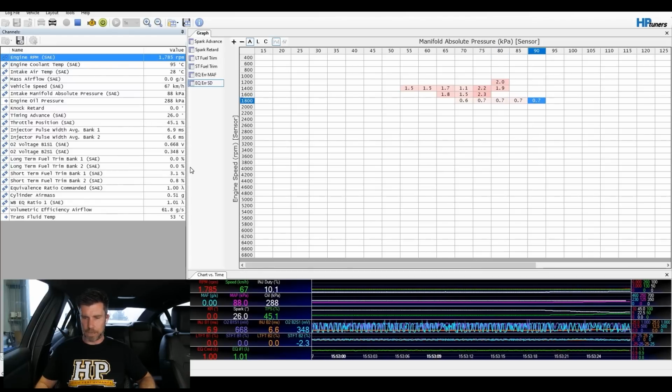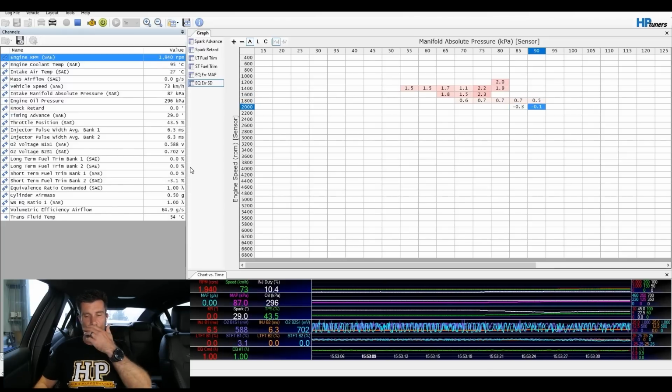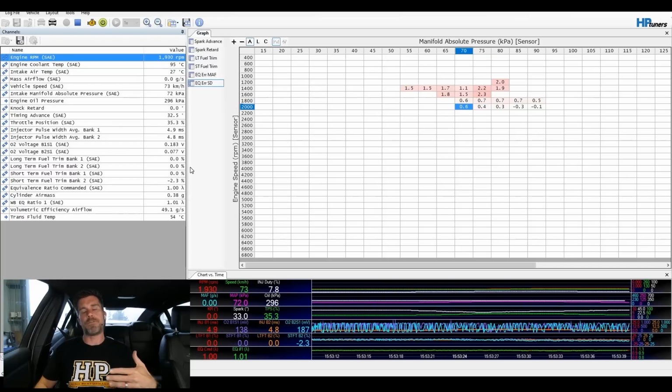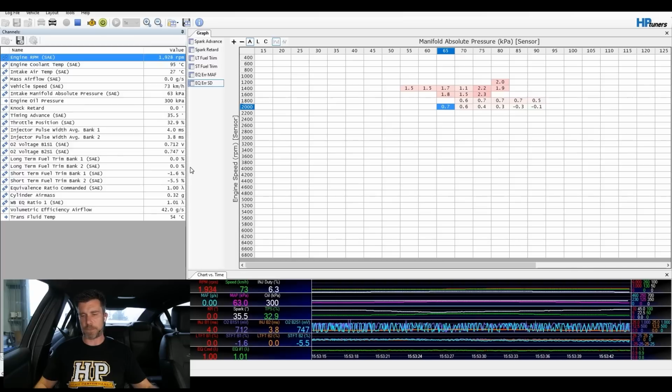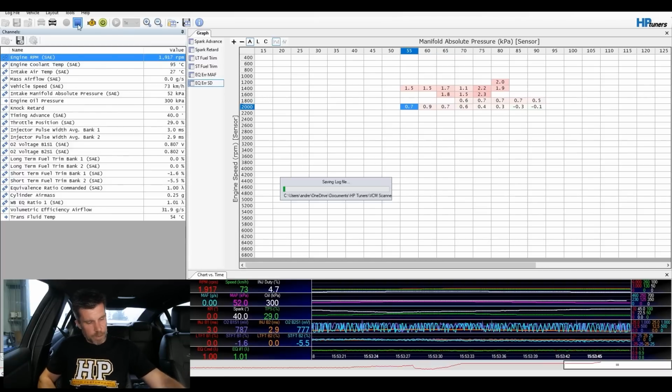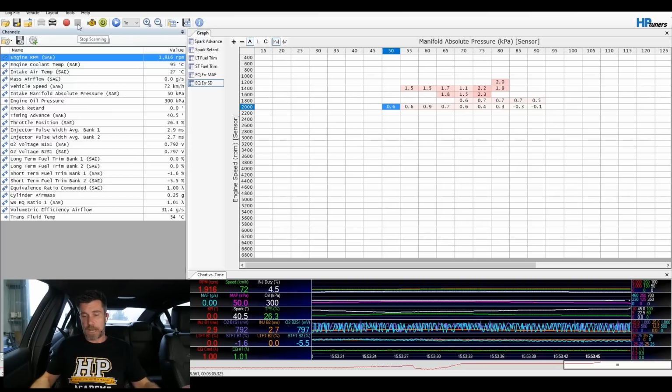And let's bring our RPM up. We'll do the same at 2000 RPM here. So again, just nice smooth changes to our throttle position, nice smooth changes on the dyno RPM set point as well. And we want to basically fill this histogram in, gathering as much data, hitting as many cells as we can. Now I'm just going to stop the recording here and back off, because essentially the process is exactly what you've seen. I'm not going to sit here for the next half an hour filling this table in, but let's have a look at what the data means.